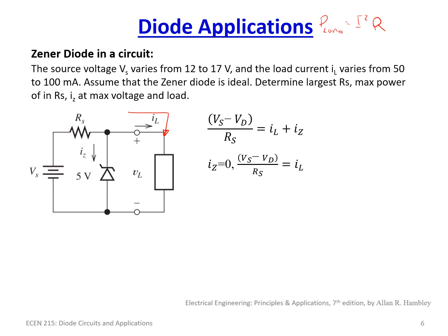So we have power and load, it's I squared R. So the current is the maximum point here. So if IL is maximized, that is going to be the point where we have the maximum load. So it's looking at that. That means IZ would be equal to 0.